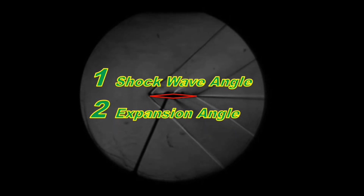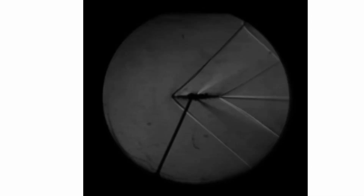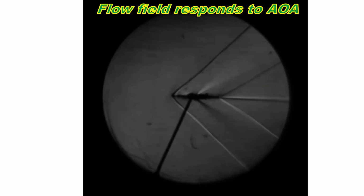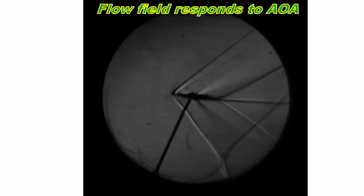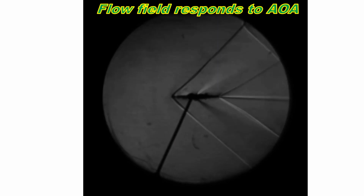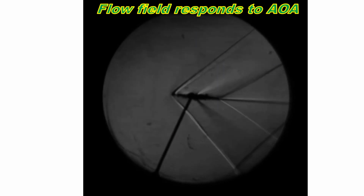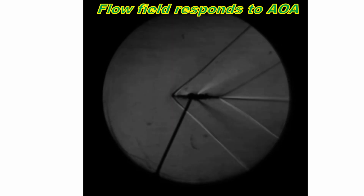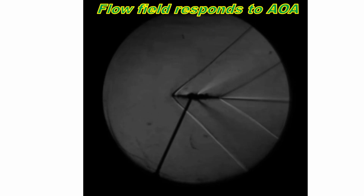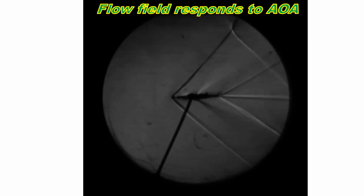In your coursework, you have to measure the angles of the shock wave and also the expansion. It will be interesting to see how the flow field responds when you change the angle of attack. You can see the flow does change a lot, and similarly, you should be able to measure the angles and compare with your simulation and theoretical calculation.